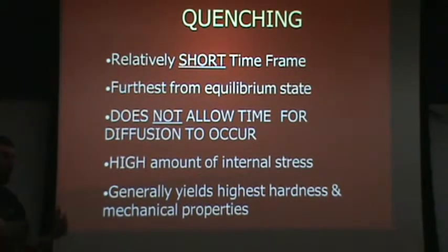So that's what will happen. We'll take these parts, we'll cut up one or two of them, try to better understand what was the initiation point for the cracks, and then how we can tweak our model to predict that more accurately, and then figure out how to change the geometry or change the alloy to eliminate the problem. Or maybe change the quenching practices.